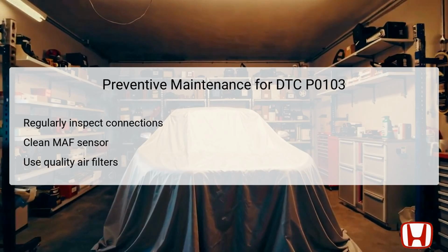Additionally, it is advisable to clean the MAF sensor at regular intervals, as dirt and oil accumulation can disturb its operation. Using quality air filters helps ensure that the air entering the engine remains clean, thereby protecting the MAF sensor from contamination. Consistent preventive measures significantly reduce the risk of experiencing DTC P0103 in the future.